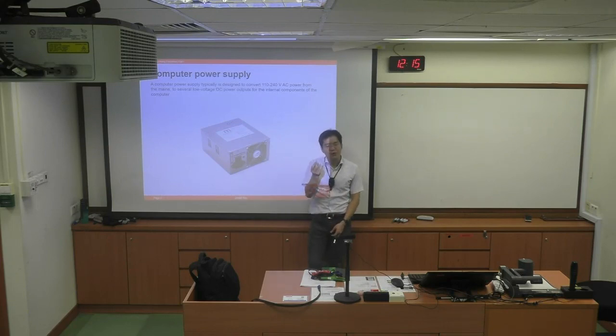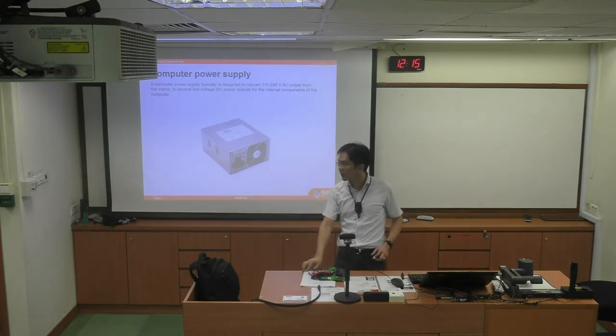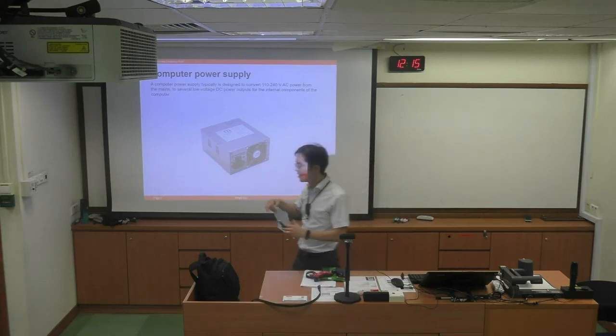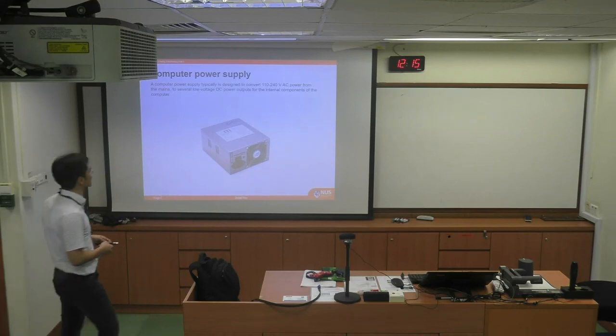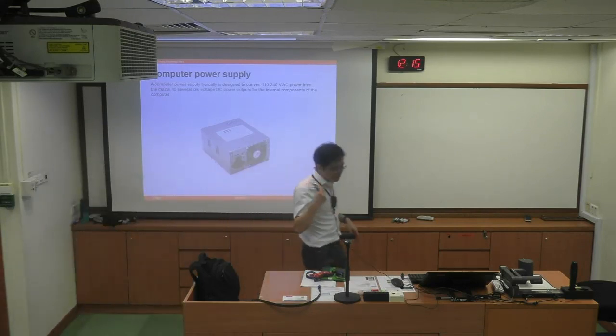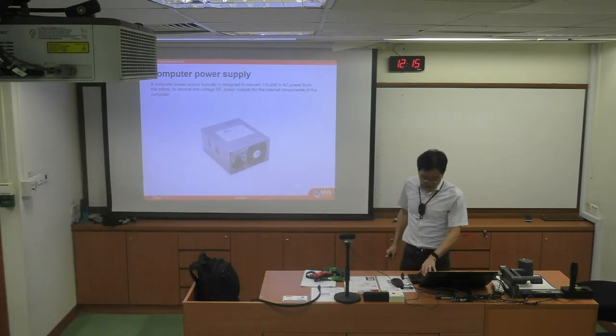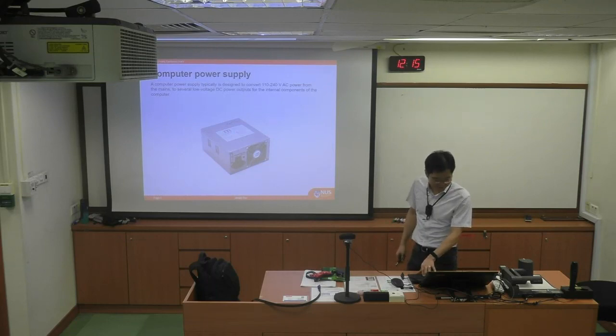That's a small failure, but as I said, the power supply these days is the prone unit that may fail over time. So you need to watch out for any appliances that die. It's most likely the power supply or the interconnect that fails. And the good news is that I replaced the power supply unit, and now the server is back on.